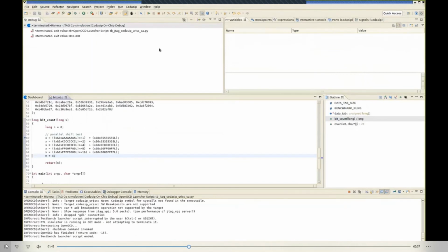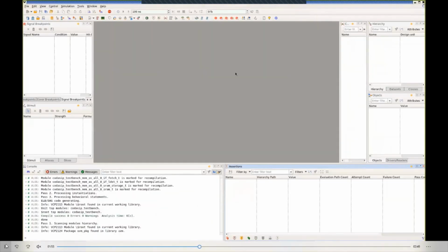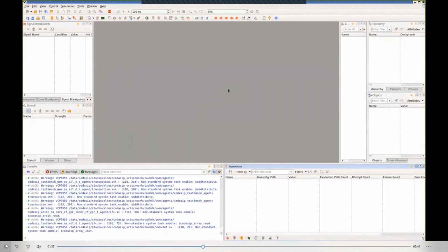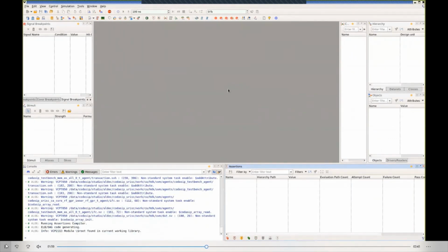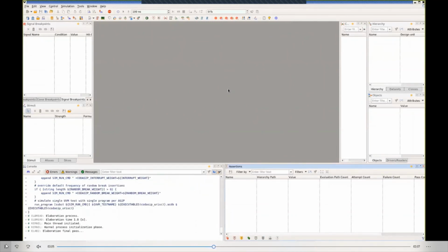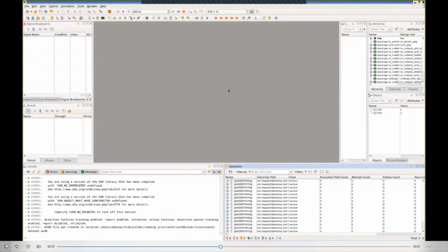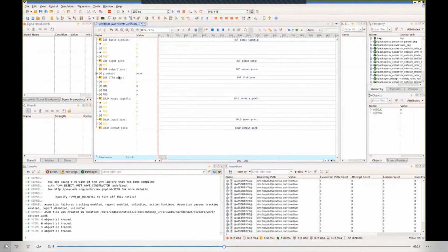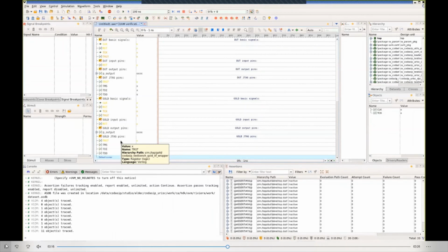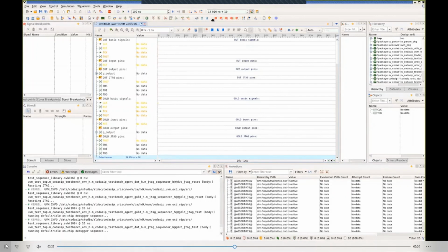The next example that we would like to show is to run a third example, which is the UVM. And in this case, we are verifying the RTL against a golden reference. So here the elaboration process starts, and we now have a fully elaborated UVM. We're adding interesting signals from both the golden reference and from the RTL. And the simulation continues to run.